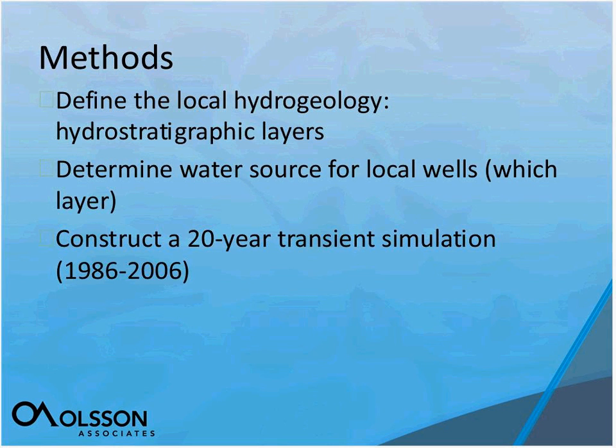And the reason that we do this 20 years in the past is we've got good precipitation data, we've got well pumping data, and we're trying to predict the future, obviously. But we use the information from the past. We develop a model, we simulate the groundwater conditions, calibrate it to make sure that we're in the right range of flow patterns, and then we turn on the new wells and see how they would impact the system. And that's really what this 20-year transient simulation is all about.